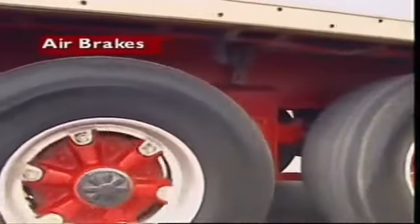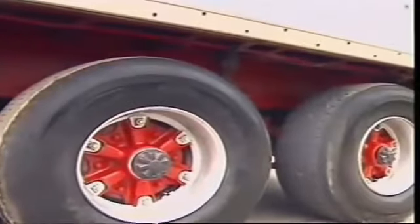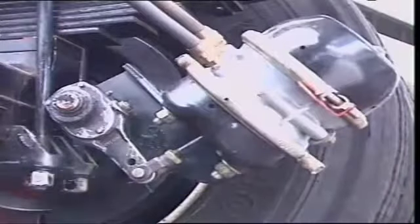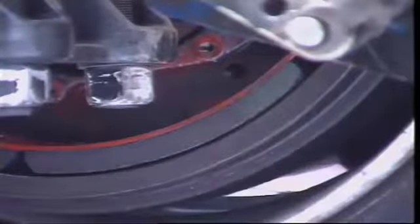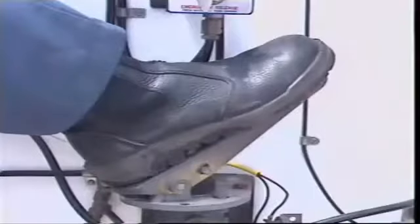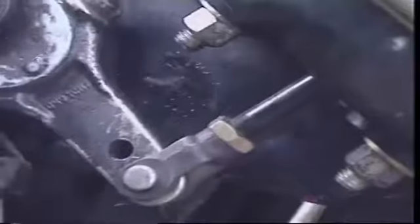This section examines air brakes. Air-operated braking systems are used on heavy vehicles. Compressed air, operating on large diameter diaphragms, provides the large forces at the brake assembly that are needed. An air compressor pumps air to storage tanks. Driver-controlled valves then direct the compressed air to different wheel units to operate the friction brakes.